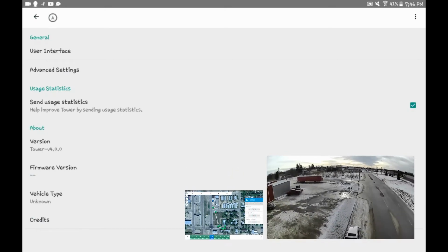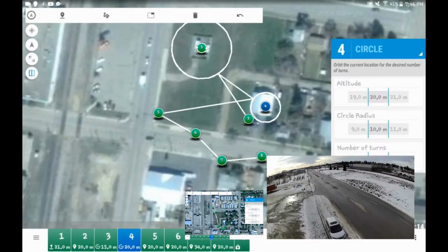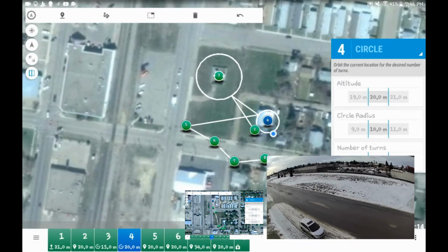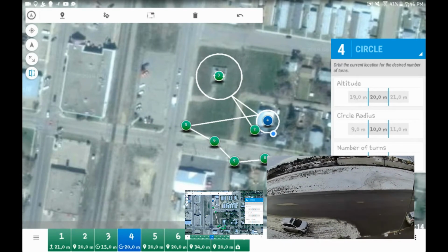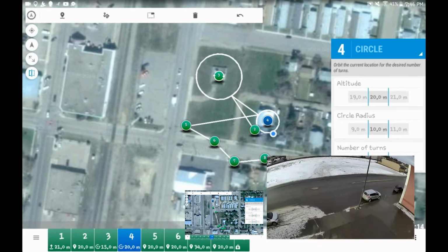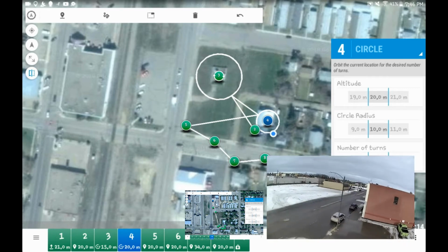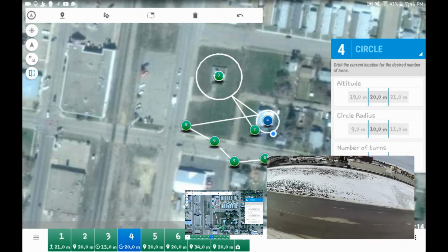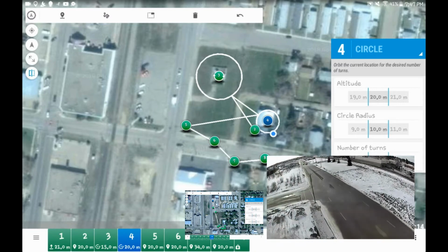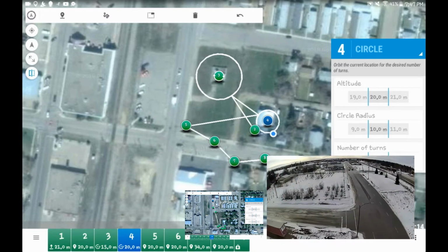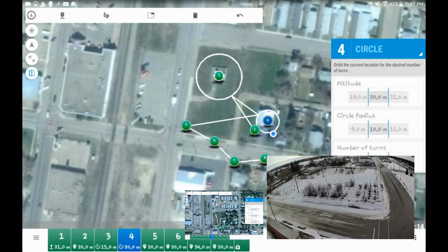Let's say there's a few things to mention on this mission. When you're flying an auto mission, the drone will return to you if it flies farther than your fence limit. So there's another video that I made with fences. Watch that. I'll show you how to change your fences. Or it flies back to you if it loses control of the signal or the transmitter.